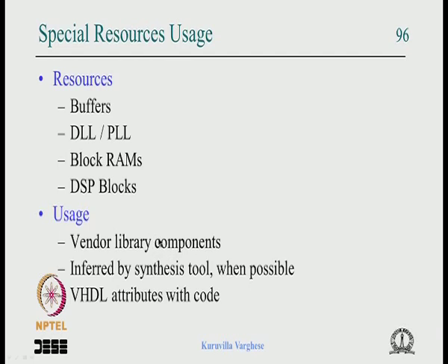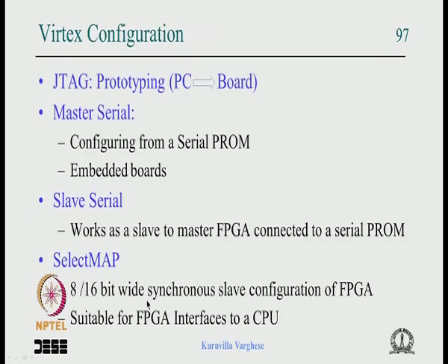If you use vendor library components and you translate this FPGA design to another FPGA from another vendor, you have to change those components. Or if you are taking this FPGA-based design to ASIC, which is usually the case because ASIC designers will do the prototyping in FPGA and move to the ASIC, all of that has to be changed in the ASIC design domain. That can be avoided by using VHDL and attributes, and so that is it.